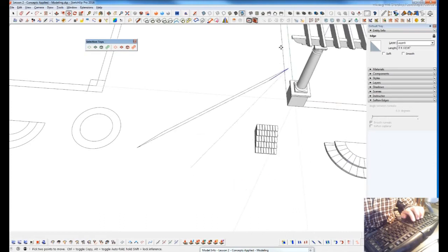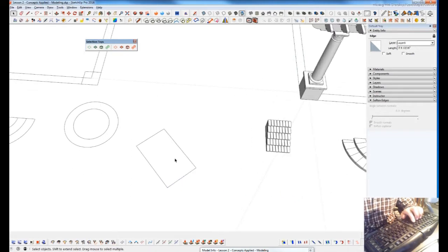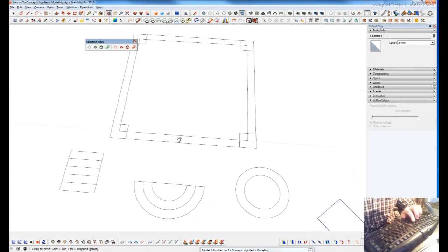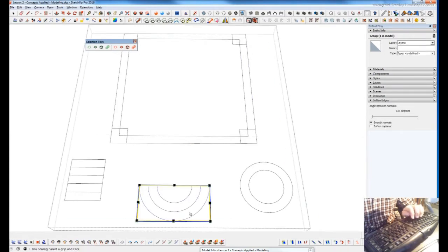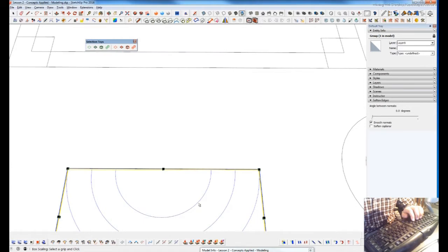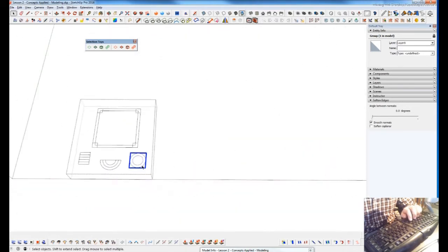There's nothing for it to snap to because it's not aligned to the axis of origin. But I could easily grab that and then grab the Fredo Scale option, and now I can scale and manipulate this in the direction here, and I could also set a direction that I wanted that to go. And it will align itself to things like that.